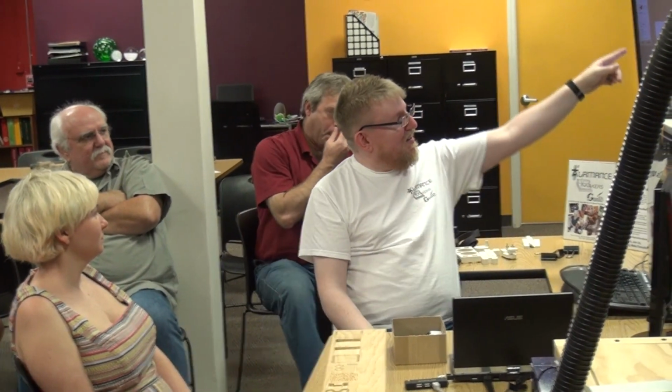So we've got our blank, and we've got our origin that allows me to design things. If I want to put something 1 inch over and 1 inch up, I can start from this 0,0. And that's how we're used to looking at coordinates. You can adjust it and put it wherever. You can tell it whether you want to work in inches or metric, whichever way you'd like to go. So I'm going to accept this.